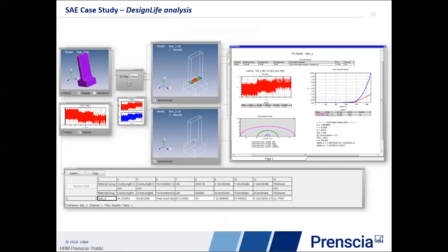The stress profile in this part basically has a stress riser at the weld toe, and so the crack grows quicker in its width than its depth. And then finally, we specified several different crack geometries through the life of the growth, which you see down here.